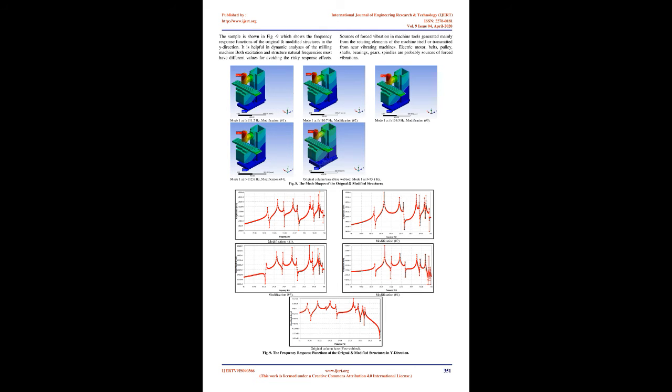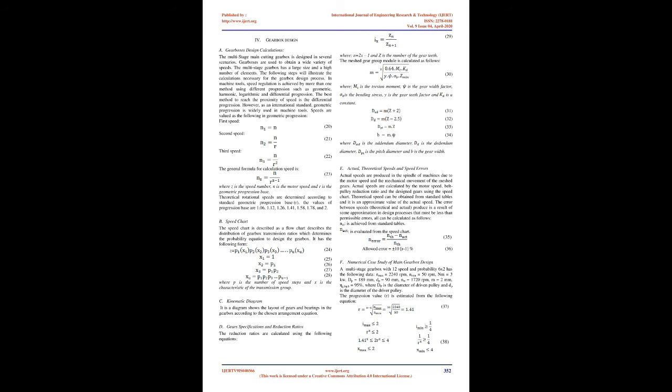Machine tool designers learn from modal analysis how potential influences could affect the quality of products made using the machine tool. Modal analysis is also important in machine tool structures where the engineer should attempt to keep the exciting frequencies away from the natural frequencies of the machine tool structure and its components.